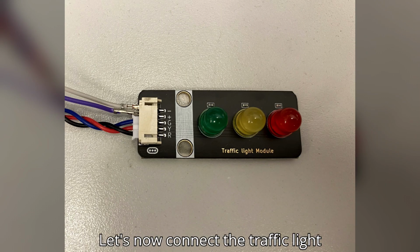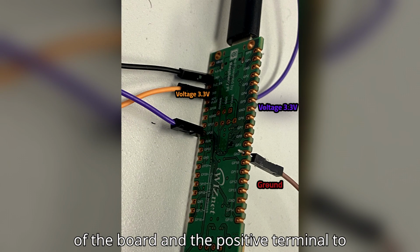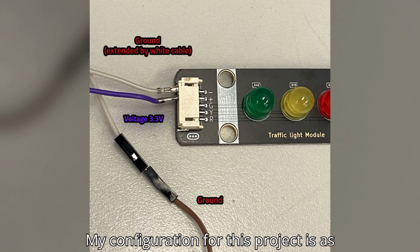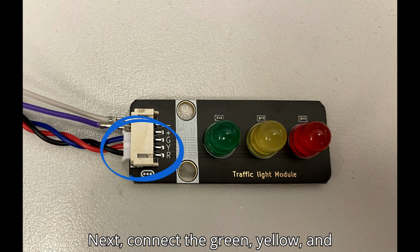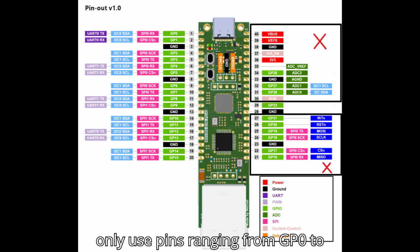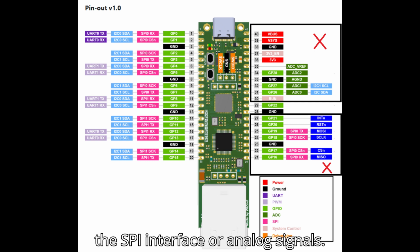If you connected successfully, a bright light should turn on if there is a power LED on your rocker module. Let's now connect the traffic light module. Connect the negative terminal to ground of the board and the positive terminal to 3v3 port of the board. My configuration for this project is as follows. Next, connect the green, yellow, and red light ports to the board. According to the documentation, we can only use pins ranging from GP0 to 15 as some of the pins are reserved for the SPI interface or analog signals.